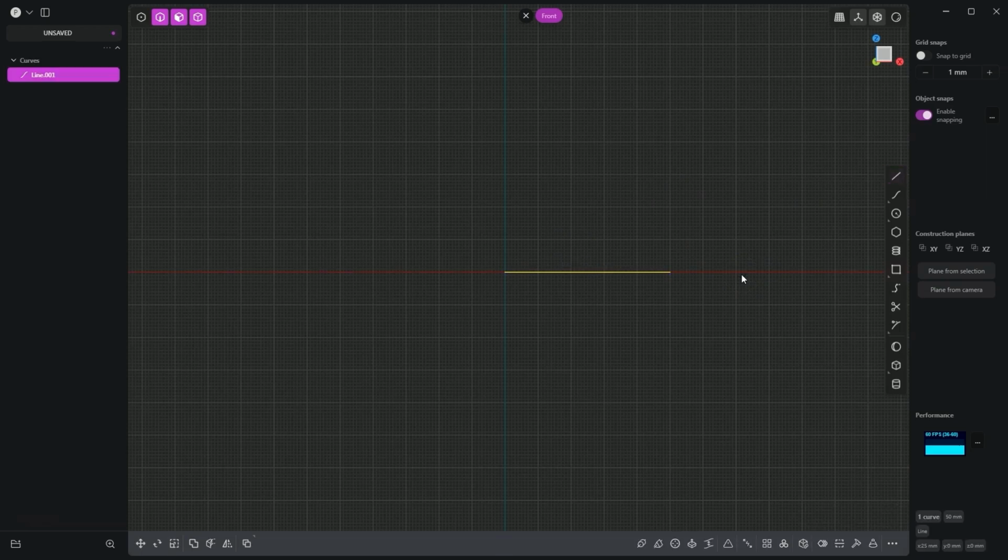If we want to create another segment of this solid, we need to select the Line Drawing command again and start drawing the line from this point. I click here, drag a bit upwards, press Tab, type 10, and this time, instead of pressing Enter, I click the left mouse button. In this way, I have confirmed the length of this line, but I have not canceled the Line Drawing command, and I can create another line.